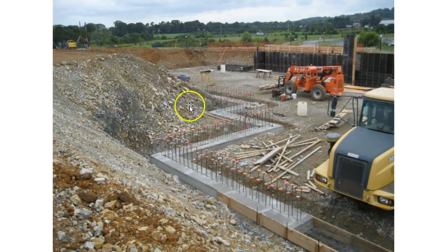So rock has been blasted, the soil embankment has been pulled back to a safe and stable incline so people could work safely, and now the footings are coming in place. We see the vertical rebar coming up. All these little orange pieces would be for safety issues, so no one ever fell and got impaled by a piece of rebar. That's an OSHA requirement. And all of those vertical reinforcements will tie into a concrete wall, which follows.